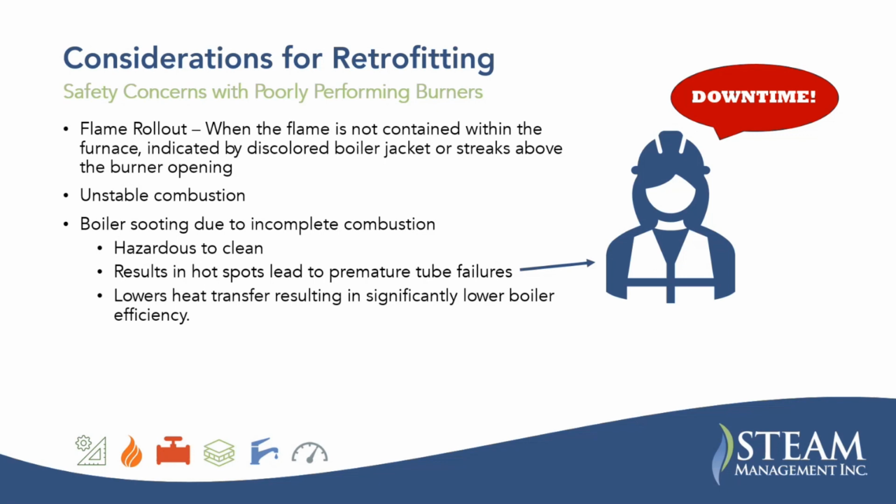And even better, it's great to have optimal combustion and avoid that situation in the first place. A lot of these efficiency opportunities come from operators wanting to avoid sooting, and so they turn their excess air up significantly to make sure that they're getting complete combustion, which works, but you're not operating as efficiently as you could be.